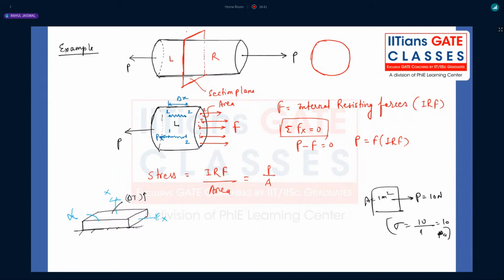Fluids also will not be able to generate any kind of internal resistant forces, but this statement is not completely true. Fluids will be able to resist when you just apply 3D compressive stresses. For any kind of tensile stress, it will not be able to generate any internal resistant forces. The tensile stress will be zero in fluids. Getting my point?